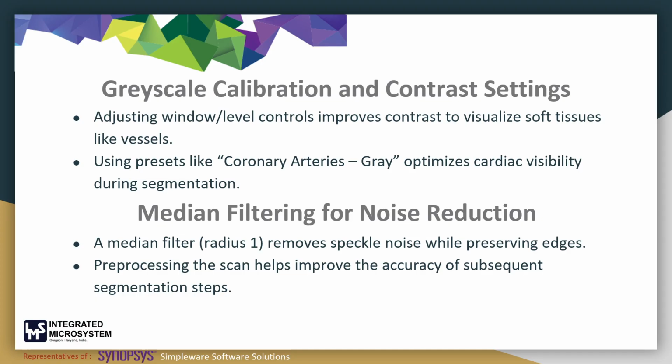Proper contrast settings are not only about clarity, they directly influence segmentation's accuracy. A well contrasted scan ensures that thresholding tools can precisely isolate anatomical features based on grayscale intensity.